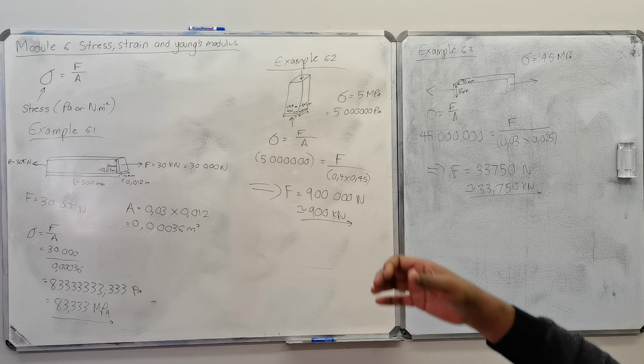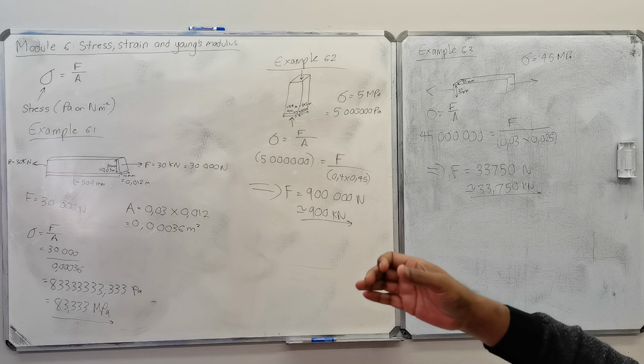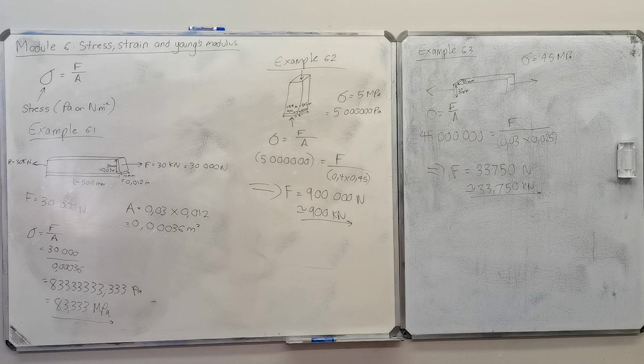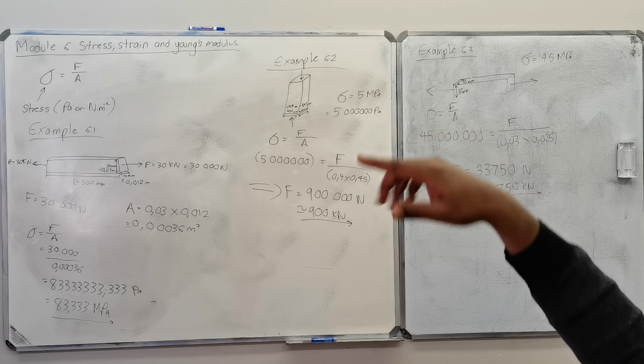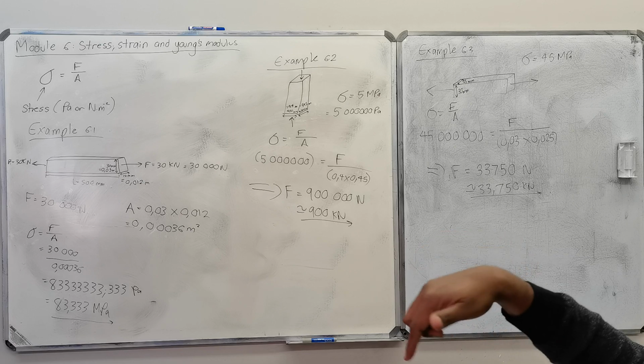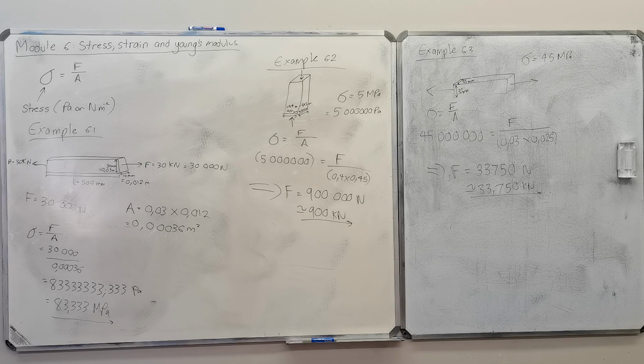So they did the calculation. The top stress on that bridge is only holding its own weight, and the bottom one holding its own weight, because the rod was supposed to stay. But they couldn't get the one rod, so they changed the design: they cut the rod and made two holes. When they did that, the top nut now held the weight of its bridge plus the weight of the bridge at the bottom. So it pulled.